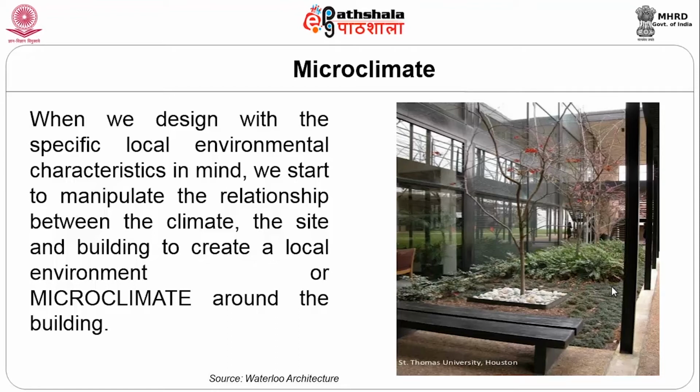Microclimate is dependent on the buildings around the place, the type of buildings around the place. If you look at Mount Road, where there is complete concrete jungle, no greenery, no break in the space, the temperatures would be much higher because of the re-radiation factor from the paved areas. Now if you look at places like Adyar or Vandalur, the temperature will vary drastically because of the percentage of green spaces to the built area. Because of the large green open spaces, the temperature will be at least 2 to 3 degrees lesser.